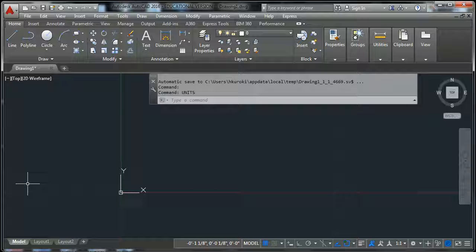The second thing when you get into a new document in AutoCAD is that we need to set up limits. Now limits is kind of an antiquated thing. We usually don't need it for the most part, but it does help in certain drawings. Limits sets up a range of area in your workspace of how big your drawing is going to be, how big your building is going to be.